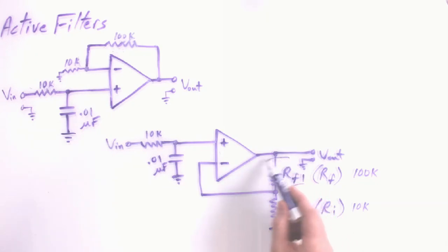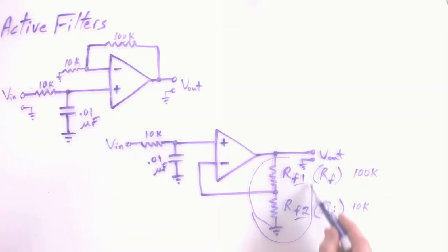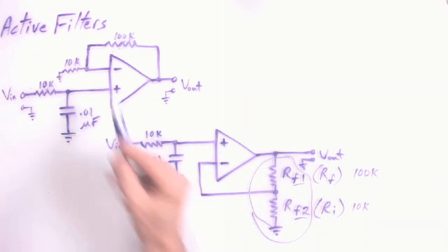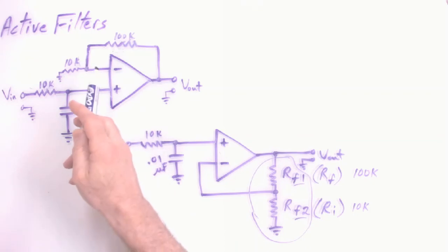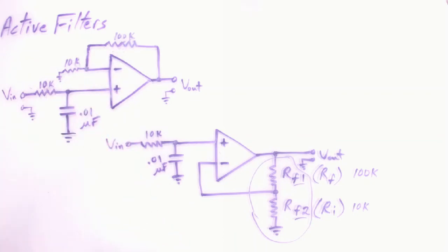And you know, this method of drawing that voltage divider, I think it is very apparent that that's what's happening. Maybe even more so than up here. It's a convention that you'll probably see if you crack open a book on active filters. Just know it's the same thing. It's a non-inverting amp using negative feedback. But like I said, in some ways I like that. I like that obvious voltage divider showing up that way on a schematic.